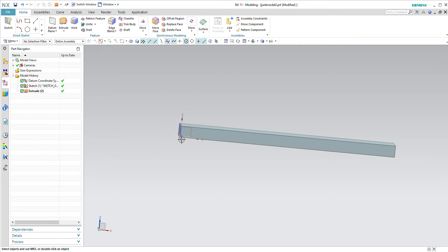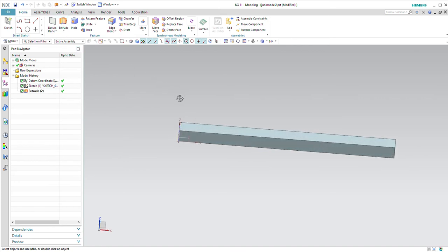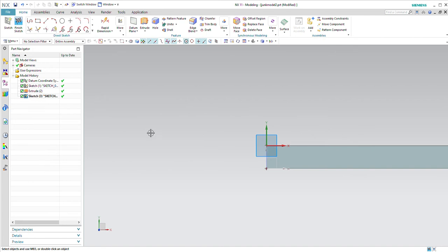I'm going to show you in a minute how to create the model out of this, but just for completeness, to do this quickly, let's say I wanted to sketch some other feature on here to make some other structure. So I can make another sketch. I could decide I want it to be on this top surface and say, okay, now it's going to orient to that top surface.